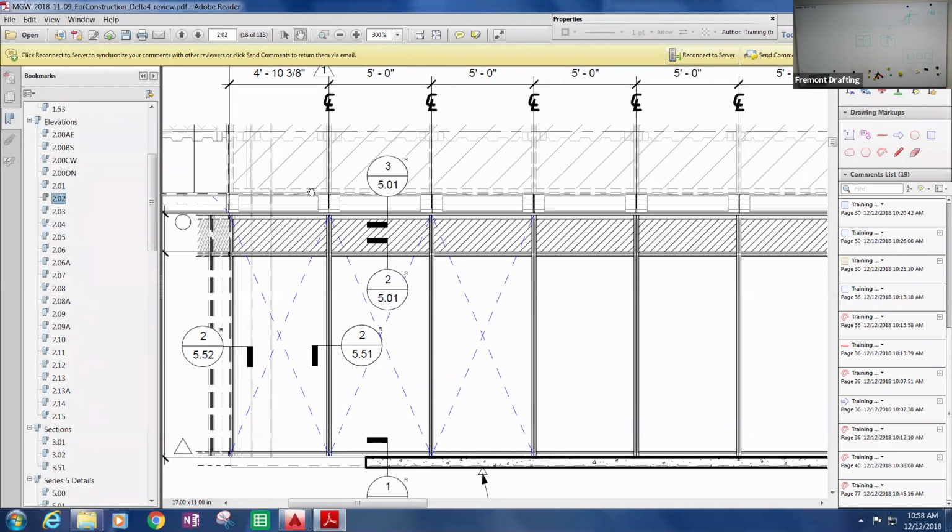So that panel is translated. That whole thing is translated, and my window is inside of that. My window is really just going to translate. Once it's in there and caulked all the way around, it can't go anywhere. It doesn't matter if I designed it to rack, it's not going to, because the caulking is going to keep it in place. So in a window box condition, that's really translating as well.